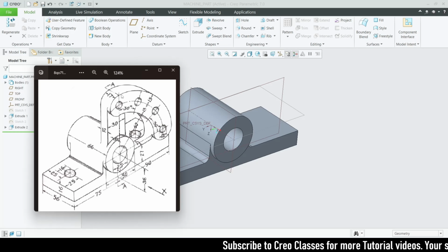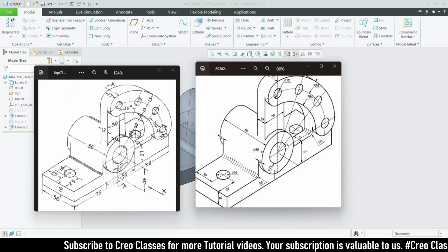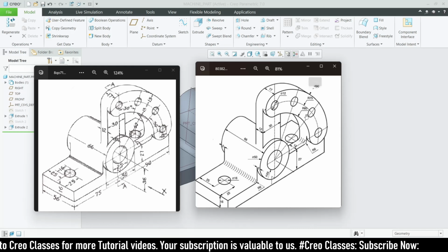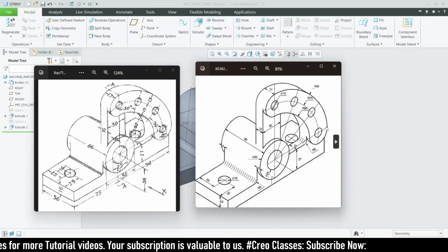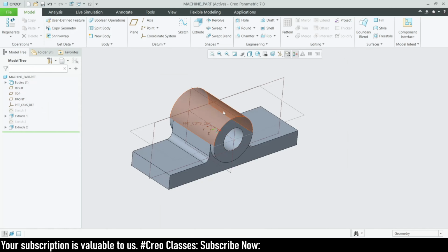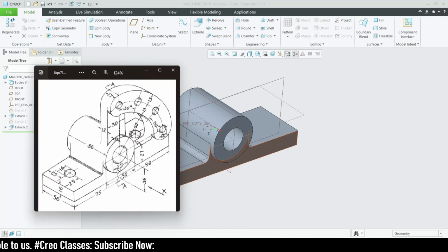So now we have to create this circular part here. Before that, we need to see the dimensions. As you can see here, they have provided the outer circle radius as 90, inner as 60, and the construction circle as radius of 75. So 60, 75, and 90. So for this sketch, as you can see, this part has a plane which is equal to this part. So we have to sketch this part equal to this plane.